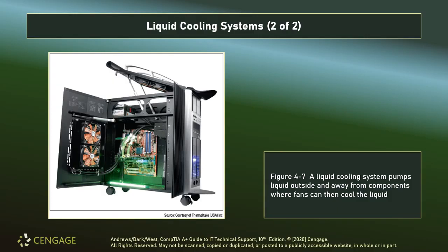They're connected to what are called water blocks, which are usually plastic. They usually use something like lucite or some other high impact polycarbonate plastic that will contain the liquid. It's then bracketed in place, has a metal membrane that stays in contact with the component being cooled, and allows that membrane to be the point of transference between the cooling fluid and the component itself. The heated fluid is then recirculated back into the reservoir.